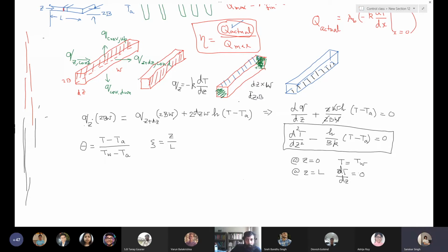Sir, here we have left out the MCP dT term, right? It's a steady state. So heat in equals heat out. So that is the heat balance for steady state. Okay, sir. Had it been unsteady state, we would have to take d by dt of MCP dT.